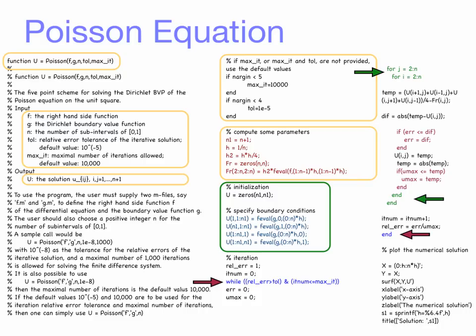And then we also store the absolute value of that temporary value and compare it with the umax that we have ever recorded. So we use the temp or umax as a storage value to record the maximum field variable value in all the interior points in all the iterations. So as we come out of these inner loop and the while loop, we will have ended up with the maximum value of u for calculating basically the relative error.